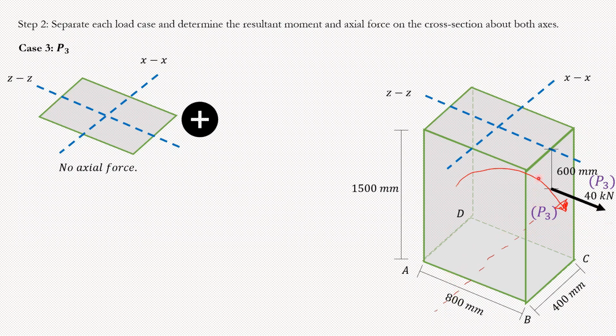Anytime you have a lateral load like this, you're going to have a moment about one of the axes, right? And by the way, remember that this force that you have here cannot really be applied with eccentricity here, because if it does, then that's just torsion. Well, to put it better, it could be applied, but we're not really concerned with its effects. The only thing we are concerned with in this case is normal stresses or flexural stresses. So it will be irrelevant for our case. As long as it's applied anywhere here, doesn't matter. The effect will be the same for us.